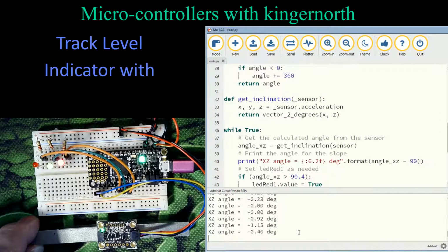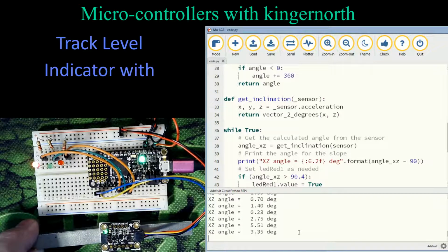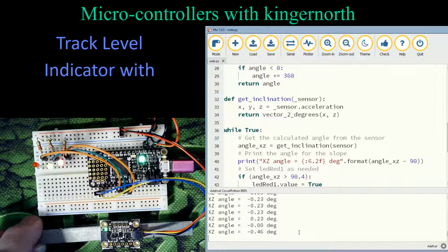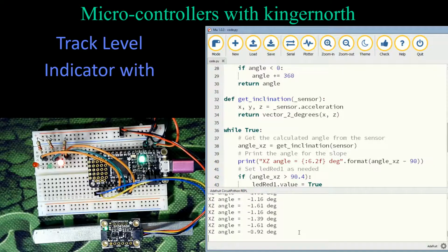And you can see on my transition, I get both lights picking up, just like I did before. And then going up, and I go the other way until I eventually just have that light on. But the green will come on as I get close, just the green, and then I can have green and red. But we can see here that we're actually off by about 1.3 degrees maybe. 1.3 is normal. There's a little bit of vibration even in the table.